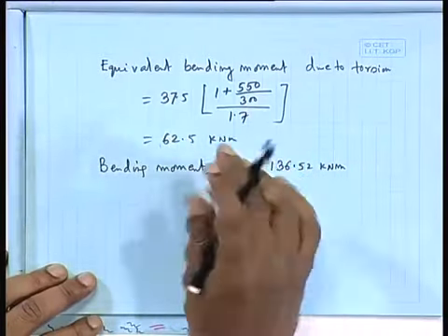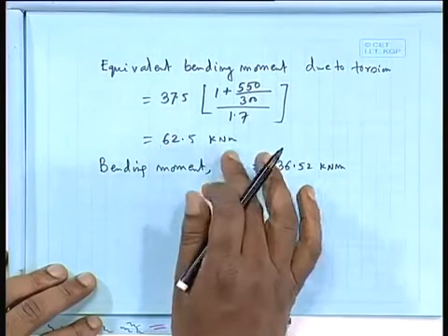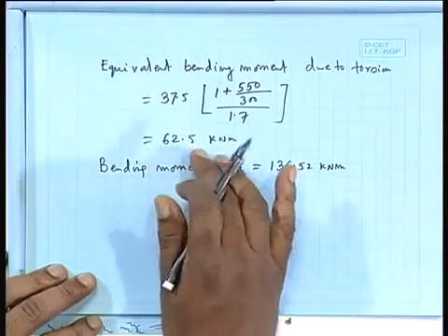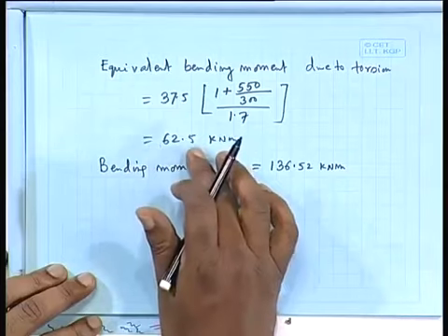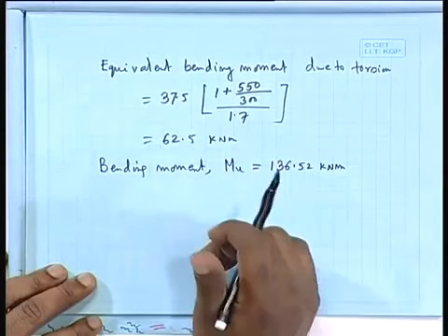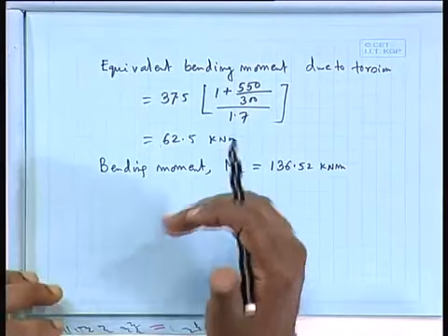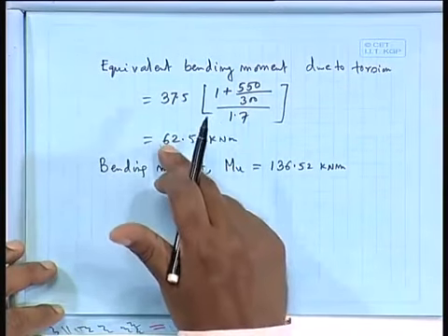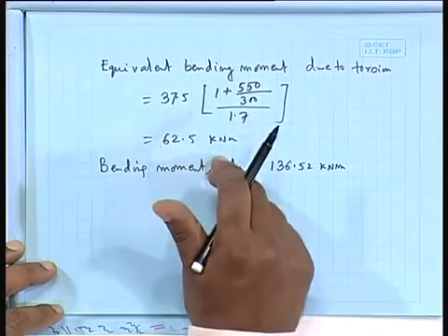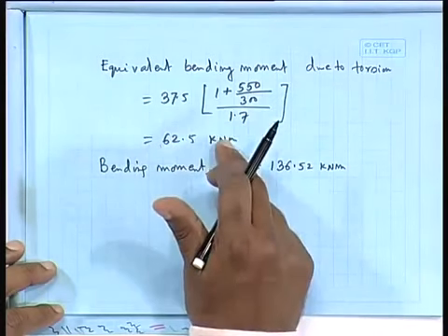For the singly reinforced section, we can again consider independently. But in actual practice, strictly speaking, you already have the reinforcement as if it is already balanced. So whatever you are adding, you are giving due to this moment.